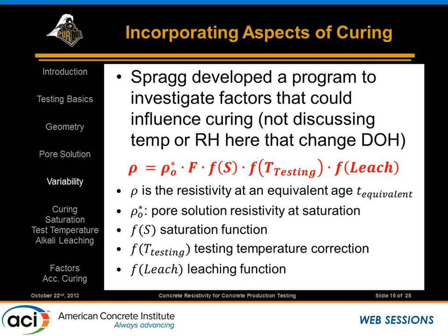So one of the things that we started to try to do was to quantify several of these different effects that we've heard people talking about this morning. So we said that this first part of this equation is exactly what we've been talking about: pore solution, the formation factor, which describes the saturated system, describes essentially the microstructure of the system. But then we're going to talk about the moisture content, the testing temperature, and the leaching.